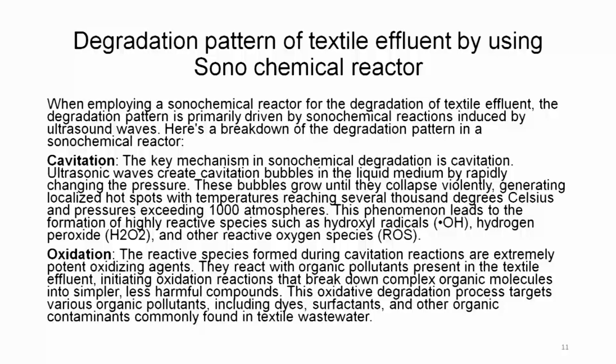Oxidation is happening due to the generation of oxidative species which are being created by the cavitational bubbles. The cavitational bubbles grow in size and then violently explode, increasing the localized temperature and pressure to be very high, where these species are generated in situ. And then they are so reactive that they immediately attack the pollutant and break it down.